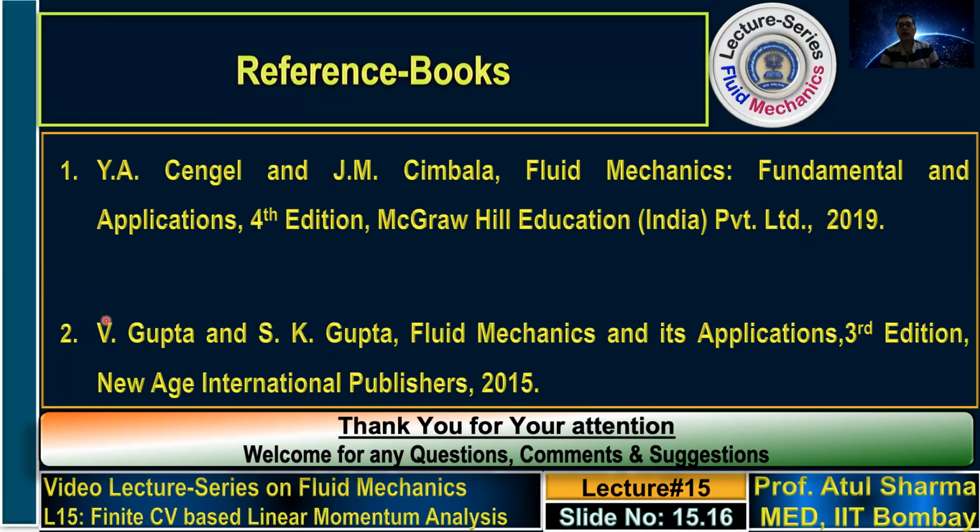To calculate Fx, you subtract the x momentum flow rate coming in from the x momentum flow rate going out. For Fy, you subtract the y momentum flow rate coming in from the y momentum flow rate going out. Thank you for your attention.